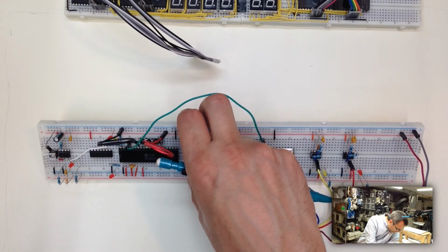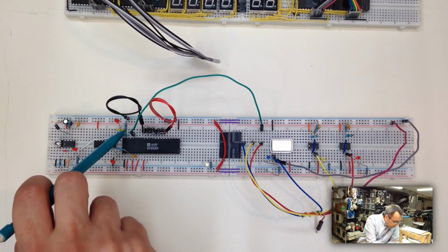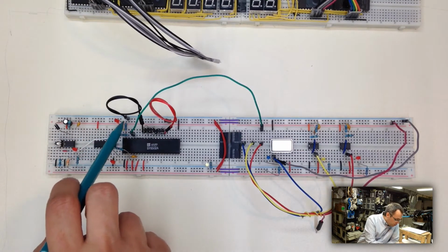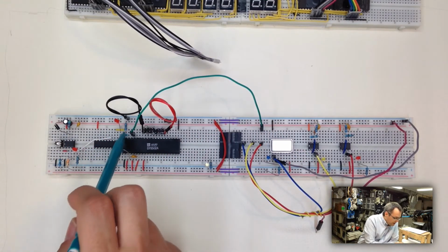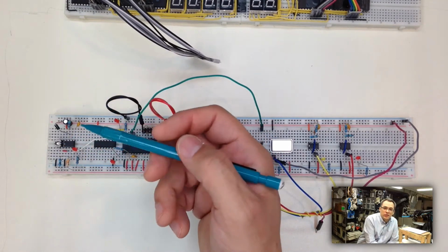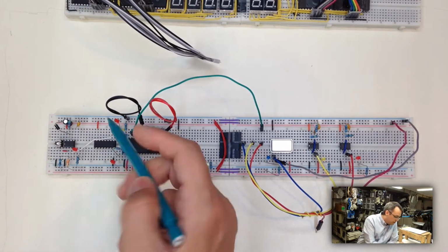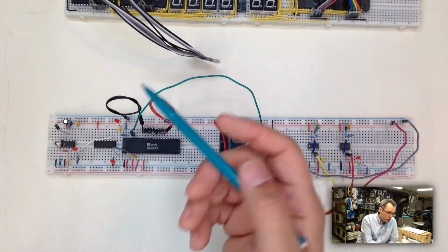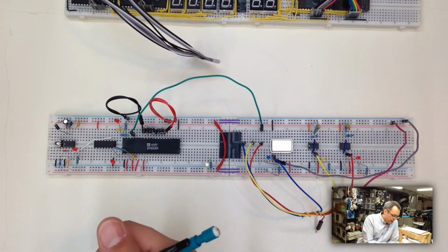200 and 2 zeros. That's a 2K. This resistor pulls this pin to positive. And then what happens is when the negative reset comes through, the negative reset has less resistance, so that signal is going to take precedence and it's going to pull the pin low, and then when it's done, it pulls the pin back high where it should be.